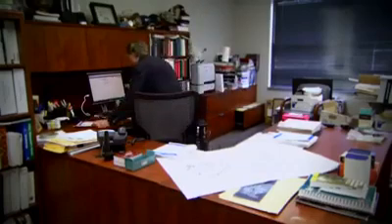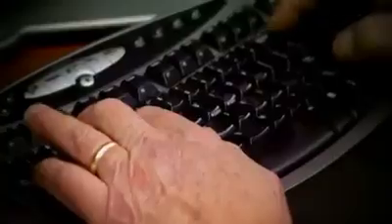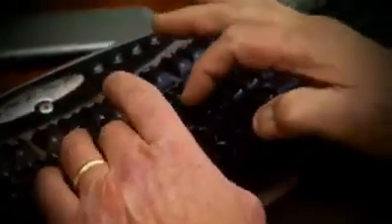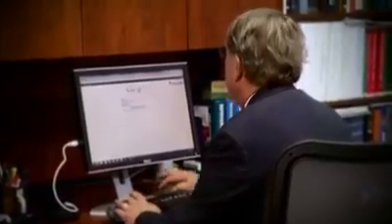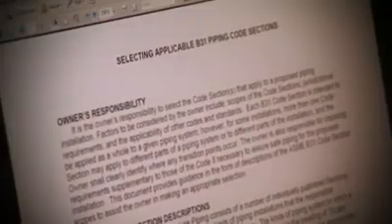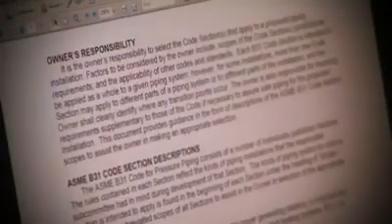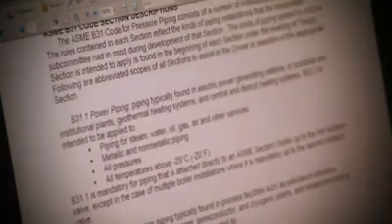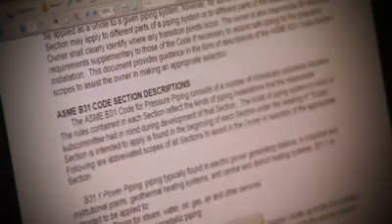To aid the engineer in this, ASME has published a guide for selecting applicable B31 code sections, which can be easily found on the web by searching on "Selecting B31." Be sure the site you download from is cstools.asme.org, so you have the official copy. This guide contains detailed descriptions of each B31 code section, which the owner and engineer can use as an aid in selecting the section that most appropriately applies to the job.